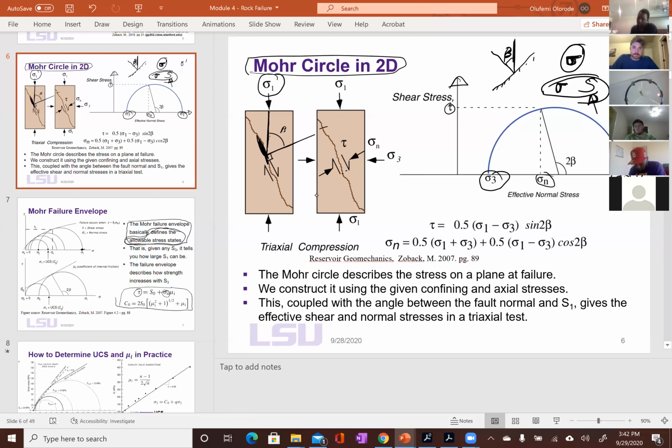Good. So this is all effective stress. And how about this? Can you have effective shear stress? No, because on the off diagonals you have 0 for pressure. So if you take away 0 from your total stress here, you still have tau. It never changes. And that's what I explained extensively in that video. Any other questions on this?